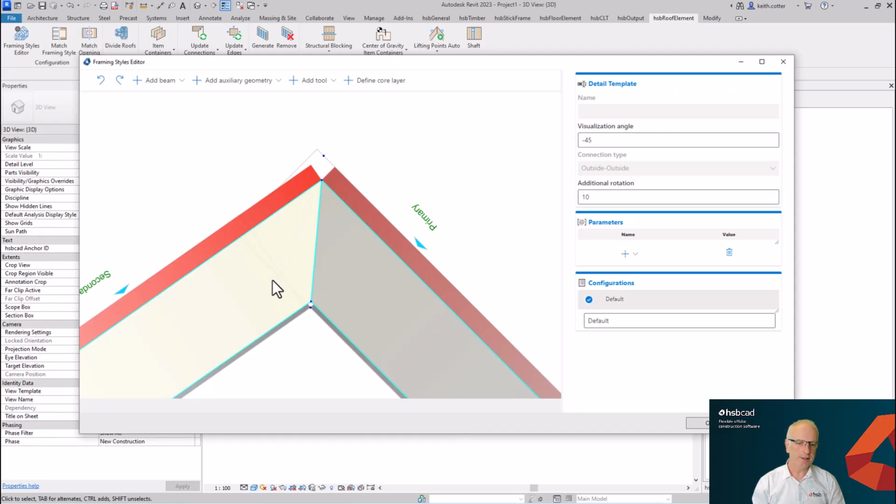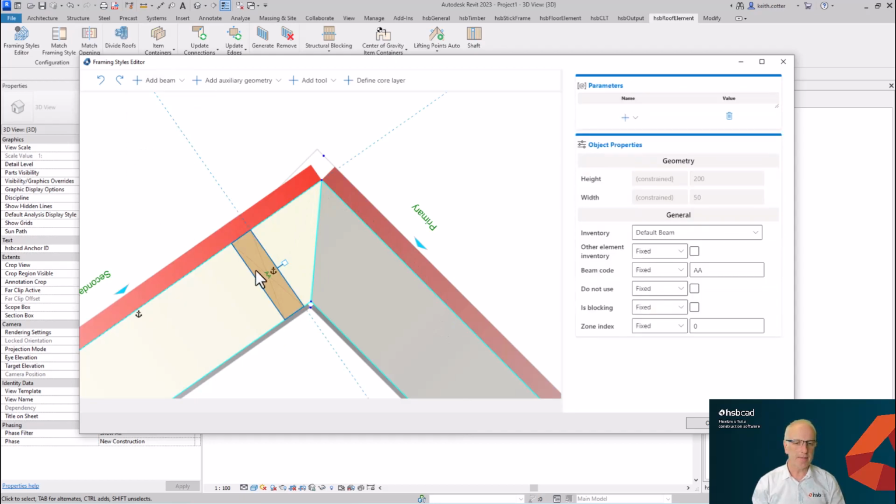So on this side I want to now add a beam, and this is a tool here where I can rotate the beam and move it into position and snap it, and you'll notice it snaps automatically when it finds a connection with these points here. Okay, and you can see it automatically found that line. So once again, let's just do that. You can see as I approach it, it'll automatically see it and snap.